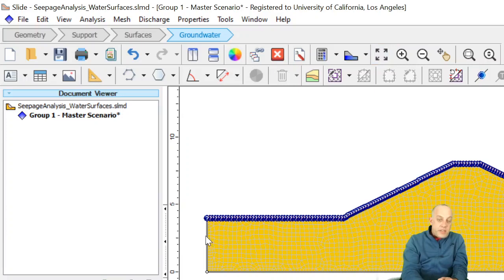Now these boundaries have nothing, right? The vertical boundaries along the edges and the horizontal boundary at the bottom. If there's no boundary condition at all specified, then that's a zero flow boundary. There's no water that's going to flow down through the bottom or out through the left or out through the right. So I might have to actually make my domain a little bit bigger to get a reasonable result, because, for example, if this water were allowed to just continue flowing horizontally, if it's going to go through from left to right, then we would want to put this vertical boundary a little further away from our domain so that it doesn't start influencing pore pressures within the levee where the slices are going to be.